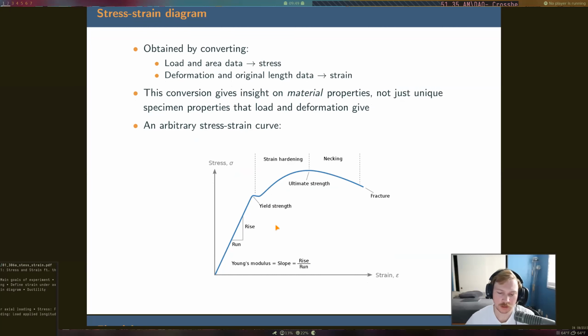Okay, so remember in our first lecture, we talked about when we are going to calculate the elastic modulus that we want to get a value that's kind of up top here. That's before our proportional limit, because remember, to calculate the elastic modulus, we need to be in the elastic range. So we want to go before, actually we can go up to our elastic limit, right? Anything after that is permanent deformation. And so I told you guys, though, that you should choose a point that's kind of far up here in your elastic range, and a point that's kind of down here in the elastic range as well.